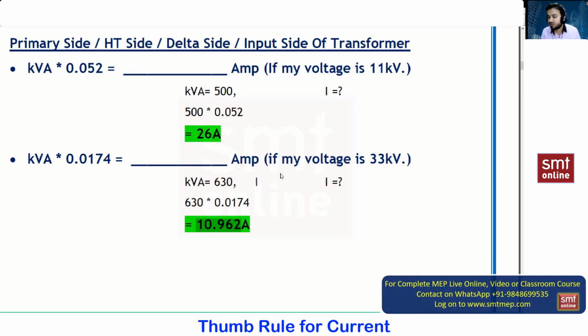The manufacturer will not specify the initial extra current for the light. You can take 20% extra of your capacity. Like they have given 1 ampere, so take 20% extra, like 1.2 ampere it may take for some time, like for 1 second or 0.5 second. Then again it takes the same value of 1 ampere. In the future, we are going to discuss all those things in chapter 4, inshallah. Okay, sir. Thank you.